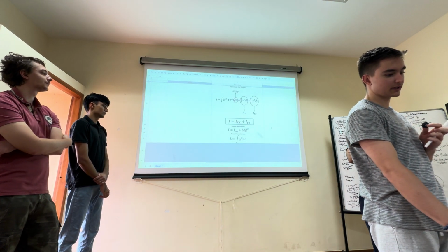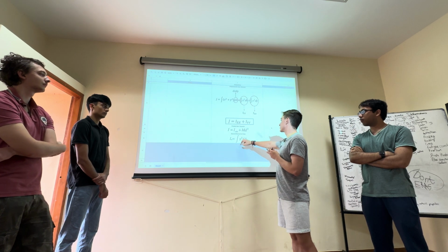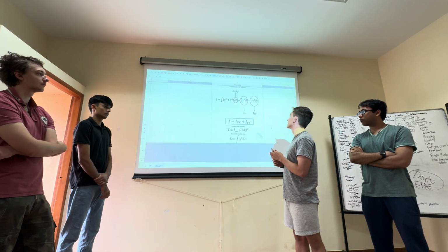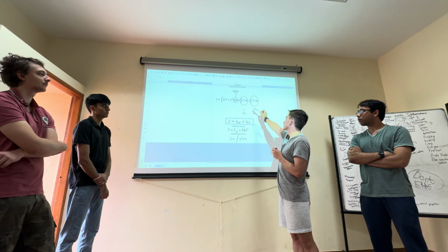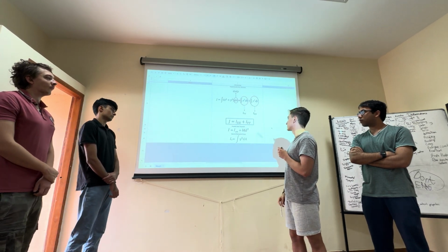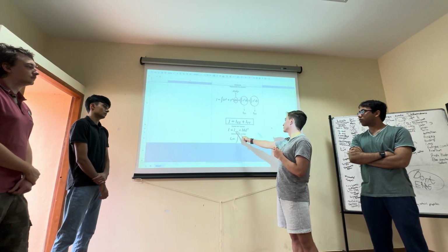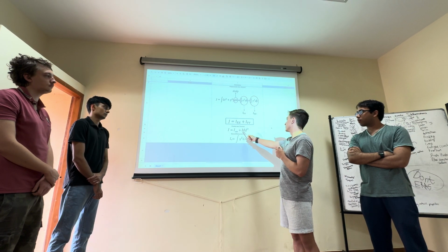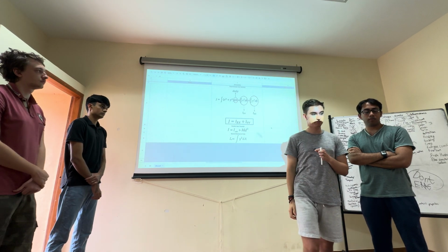And we also had the generic equation for second moment of inertia here based on its integral. We briefly talked about deriving where the perpendicular axis theorem comes from these integrals. And then of course there's the generic parallel axis theorem, where we can find the moment of inertia at any point based on the moment of inertia about its center, plus of course the distance from where that actually acts.